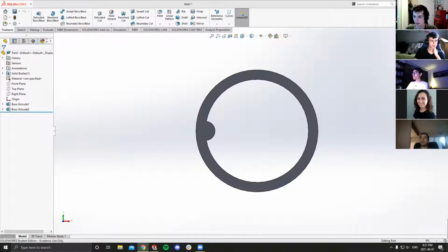And then slide 21 is the radius. So applying a radius to sharp corners is very important. As you can see in the leftmost image on the bottom row, that is supposed to emphasize what a top-down milling cutter will do when it enters a sharp corner.